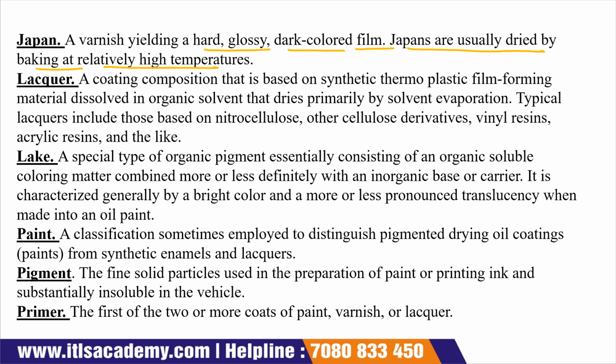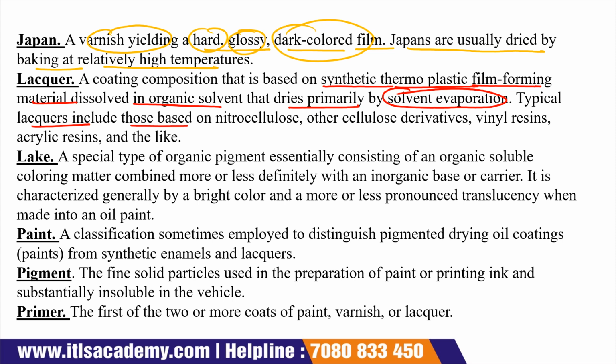Lacquer: a coating composition which is based on a synthetic thermoplastic film forming material dissolved in an organic solvent, which dries primarily by solvent evaporation. Typically, lacquers include those based on nitrocellulose and other cellulose derivatives, vinyl resin, acrylic resin, and the like.